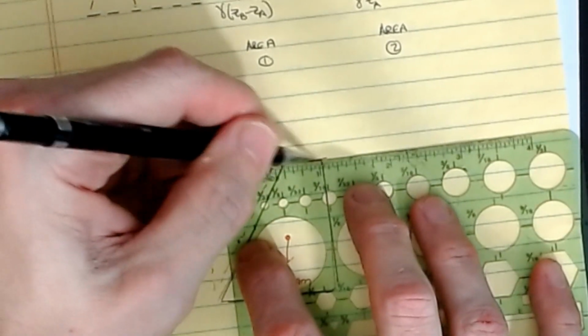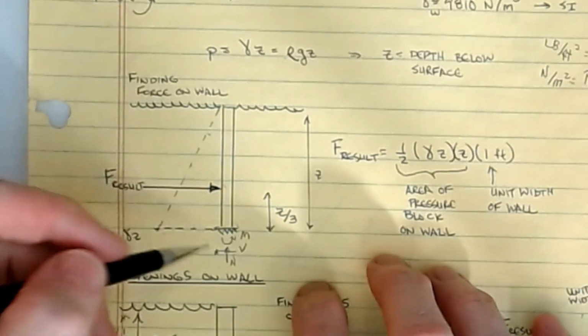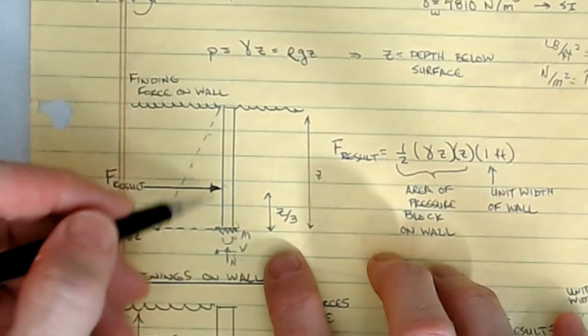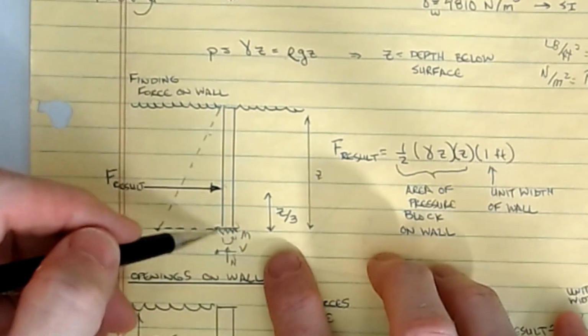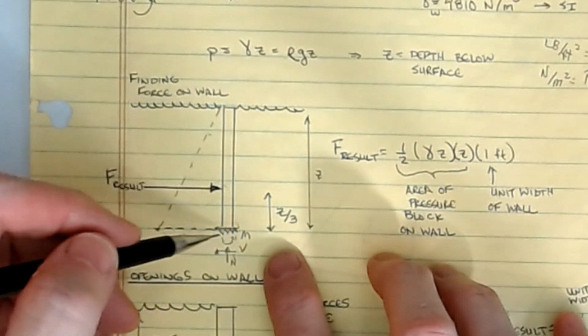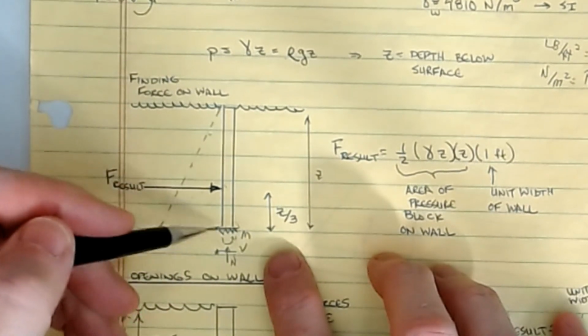Okay, now, one of the problems with some of these walls is that if we assume it's a cantilever, this is a very thin wall, so you would have to have a very strong connection at the bottom where it is embedded into bedrock or being restrained to keep this wall in place. That's one of the challenges.